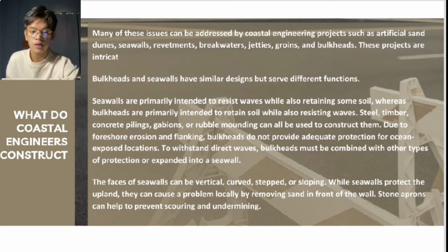What do coastal engineers construct? Seawalls are primarily intended to resist waves while also retaining some soil, whereas bulkheads are primarily intended to retain soil while also resisting waves. Coastal engineers' common projects are artificial sand dunes, seawalls, revetments, breakwaters, jetties, groins, and bulkheads. Improperly designed groins can also worsen erosion on the downdrift side.